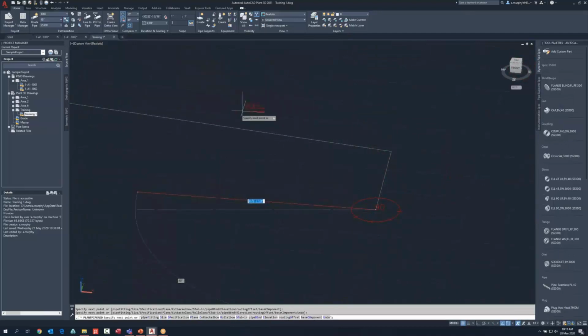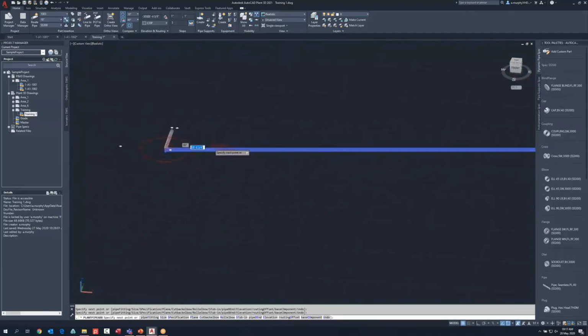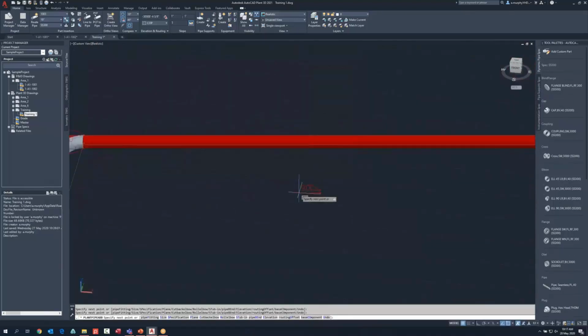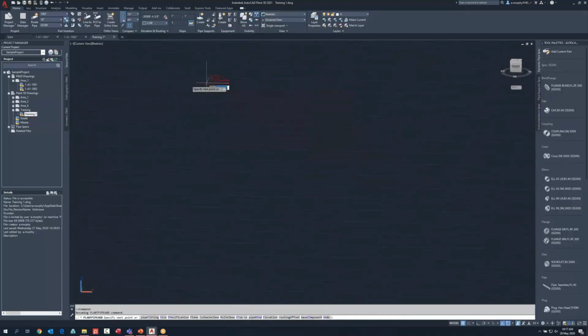So this will allow me to slope my pipe runs, essentially, rather than working on the horizontal plane or the vertical plane. I can use the slope functionality to slope pipe runs, because we all know pipe runs don't necessarily follow the perfect vertical and horizontal runs.